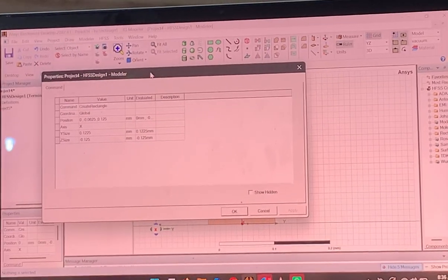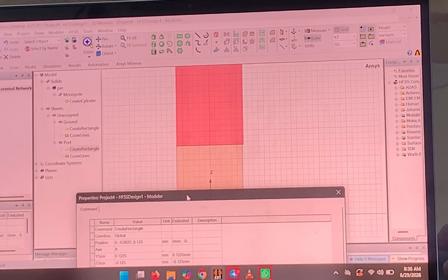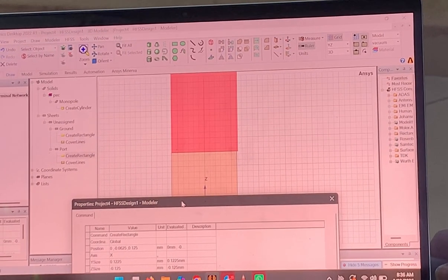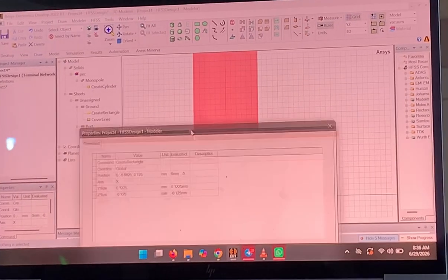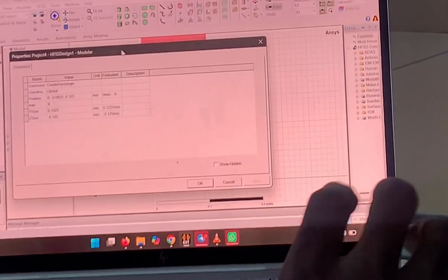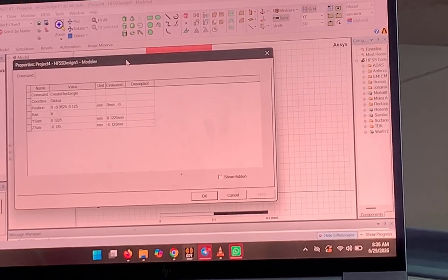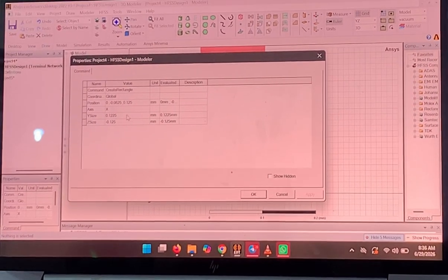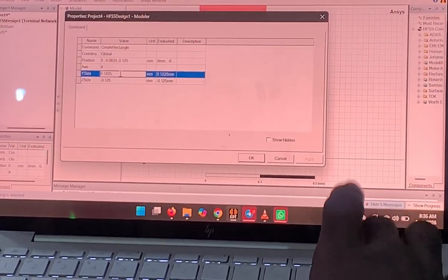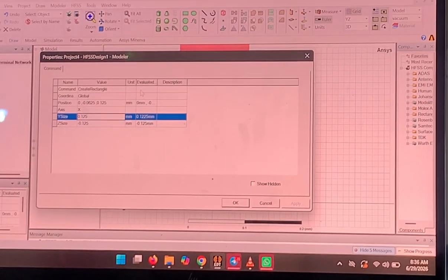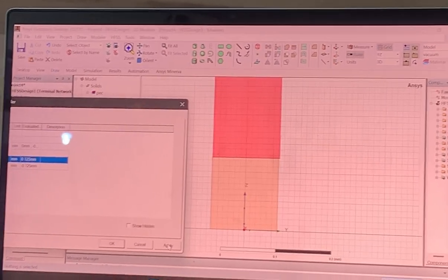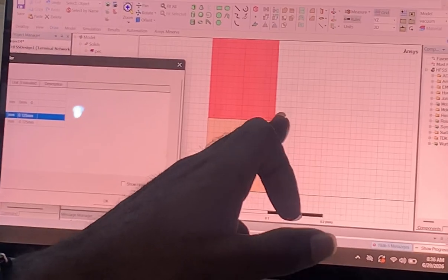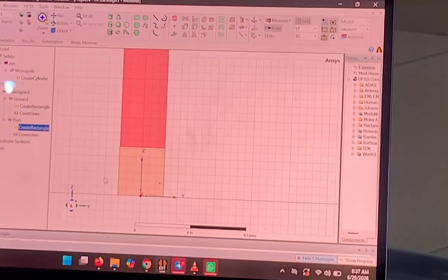So you know that the radius of the cylinder is what? Yes, and twice of that is the whole Y dimension, right? Which is 0.125. So you just come here and input your 0.125 there. When you click apply, you will see that it has shifted and is touching exactly that point. You click OK. Now basically you've done the majority of the work.